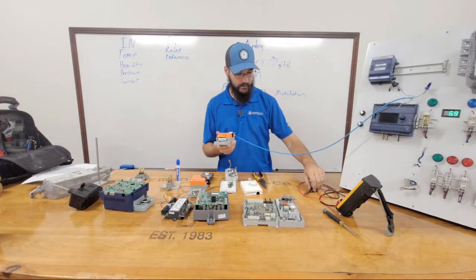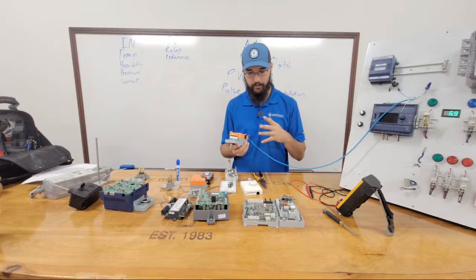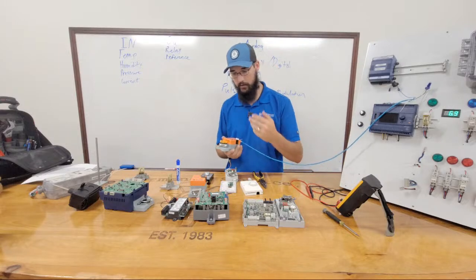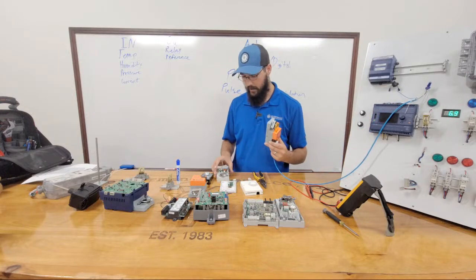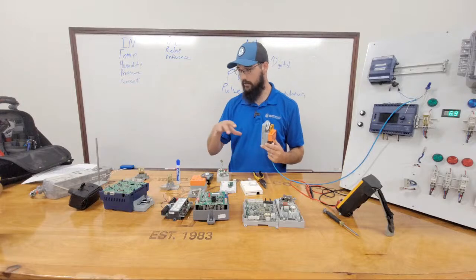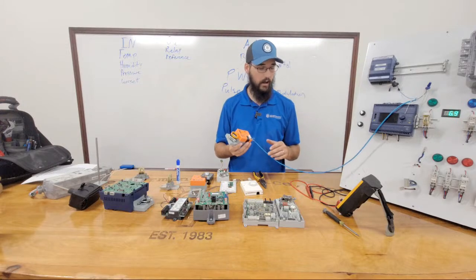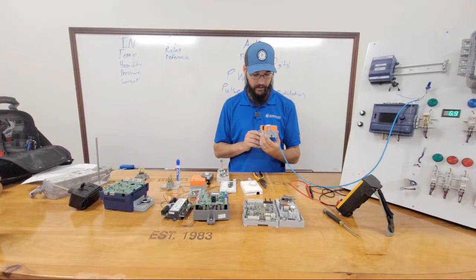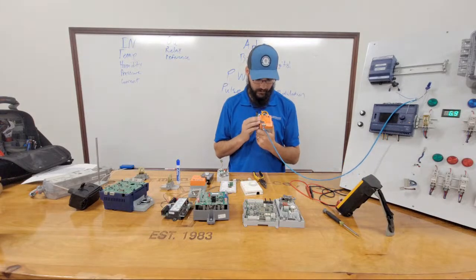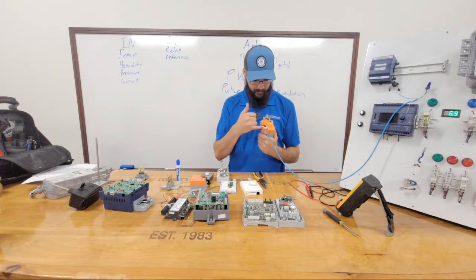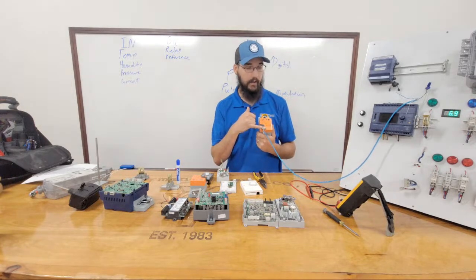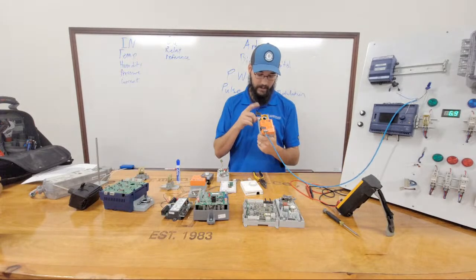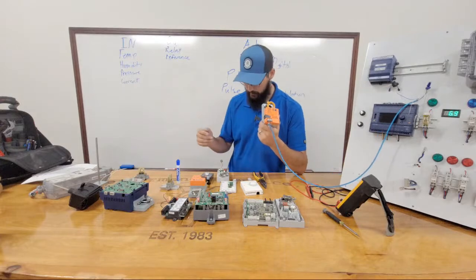So let's get into, we've pretty well covered a lot of the basics of, okay, this is an automation system, this is what things look like, this is how it works, yada yada. Let's kind of hone into each of these little components and what they are and how we can go about trying to troubleshoot them. So we'll start with our little actuator here. As I've stated, this is a 24 volt, 0 to 10 digital actuator. So we need to give this thing a signal. So right now, we have no signal obviously coming through.